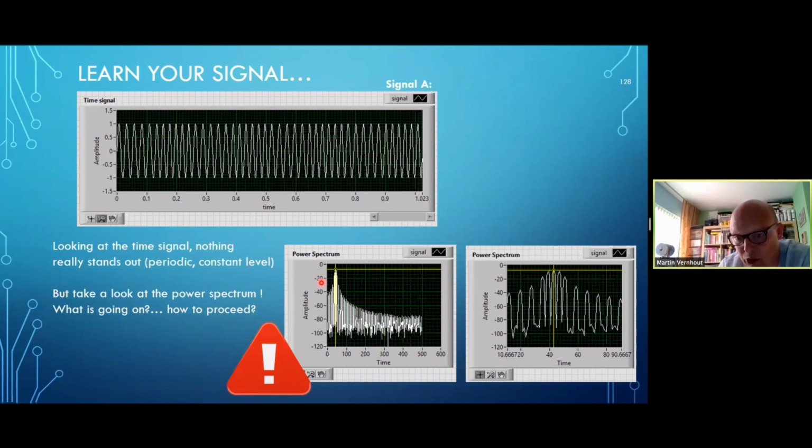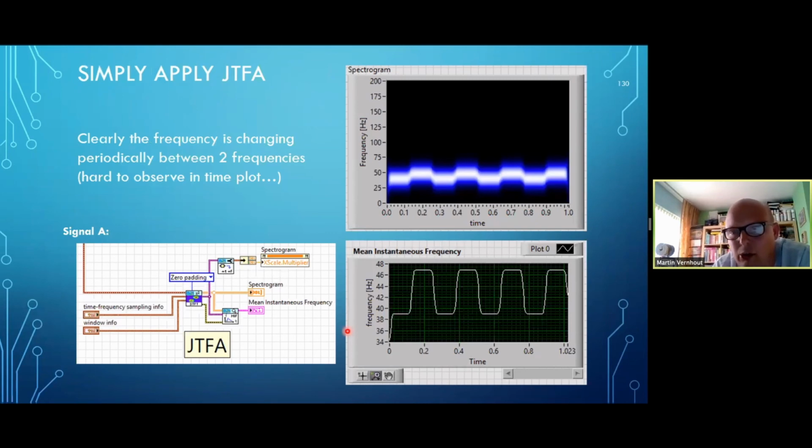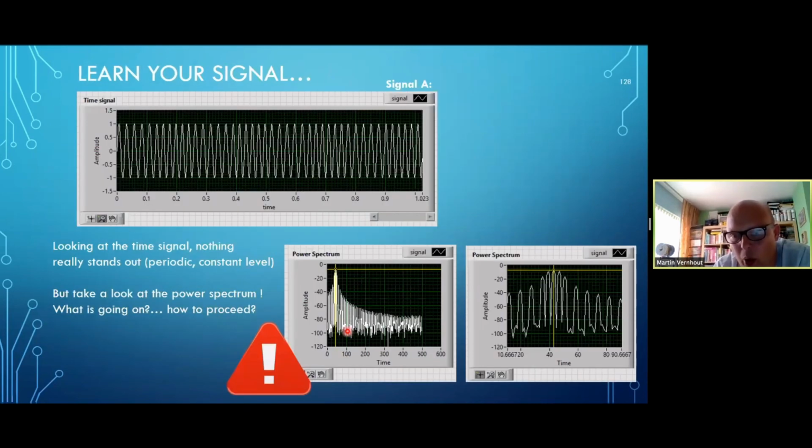So this is a normal modulated, or FSK, frequency shift keyed modulation spectrum. And the shift in frequency is actually not even that nice. It's abrupt, therefore we consume a high bandwidth. If you couldn't look at your time signal like this, you wouldn't have guessed what it meant.